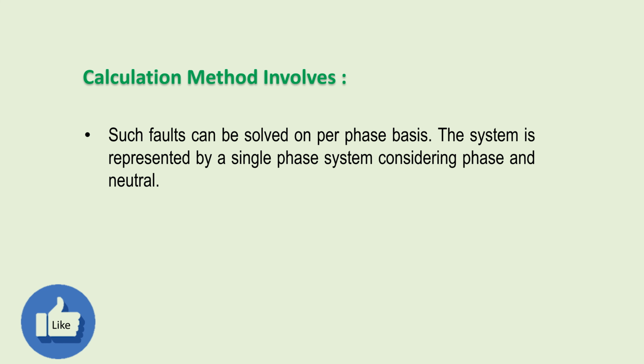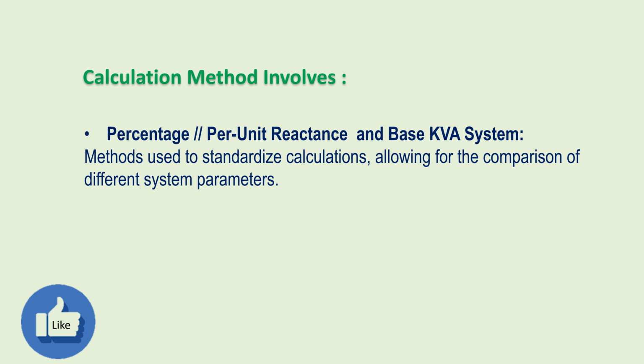Such a fault can be solved on a per phase basis. The system is represented by a single phase system considering phase and neutral. Percentage, per unit reactance and base kVA system method is used to standardize calculations, allowing for the comparison of different system parameters.